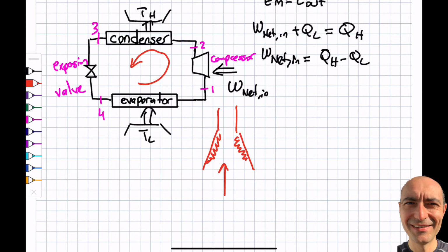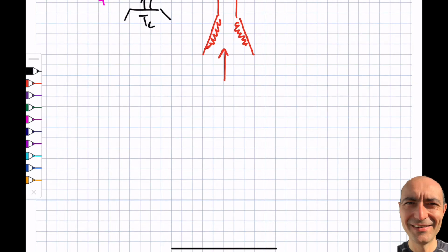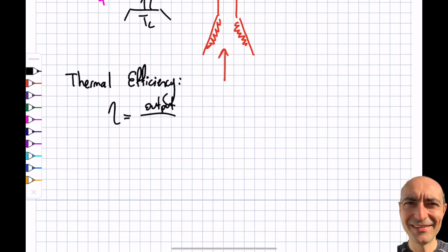But before that, I also want to talk about the thermal efficiency of a refrigeration system, which is AC and refrigerators, as well as the heat pump. Okay, as you remember, this is how we define the efficiency, the output that I intend to have versus how much I need to pay for it. This is my input. Okay, the thing about the refrigeration cycle is my efficiency turns out to be, the majority of times, more than 1. So that's why we don't use efficiency, because it throws us off. We know when I write it this way that it is from 0 to 1, and this is above 1. So we use something called a coefficient of performance of a refrigerator.